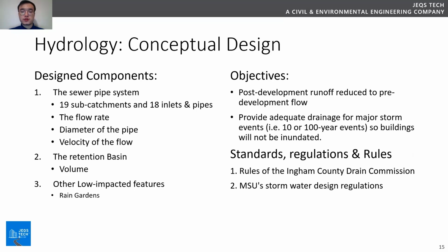In general, according to the project requirements, the company needs to design a new stormwater storage system for the project area. The design has to ensure that the new system can accommodate the 10-year storm event runoff to be allowed from the regulatory perspective, and the system is acceptable to the public. Meanwhile, the system has to be cost effective. In order to achieve this objective, the company needs to do the hydrological analysis of the surface runoff, hydraulic analysis of pipe flow, and determine the diameter of the stormwater pipes.